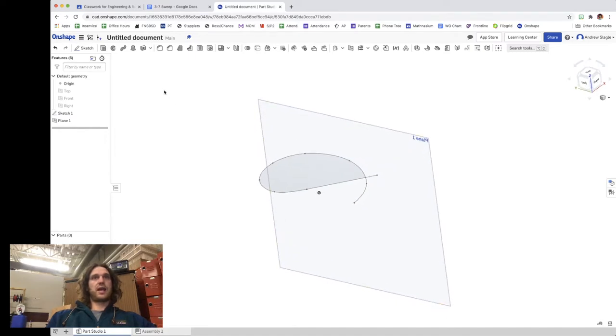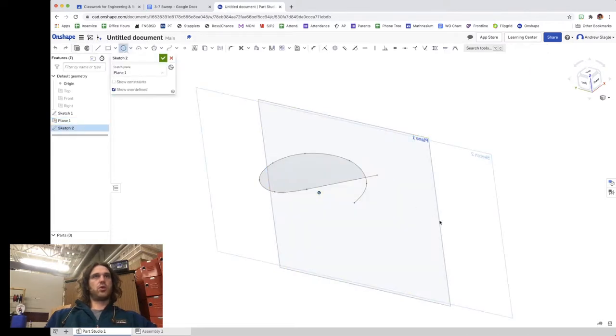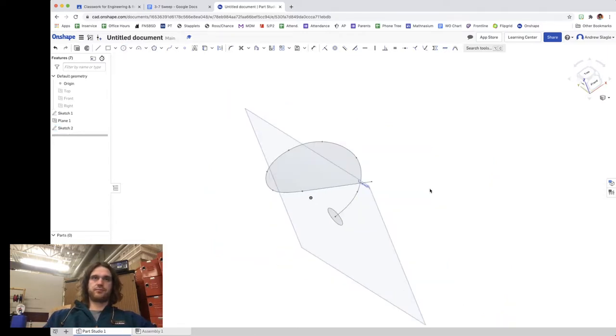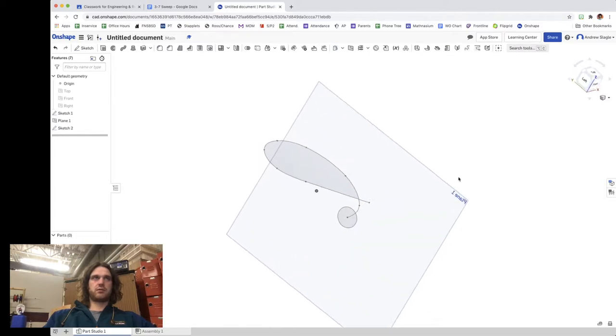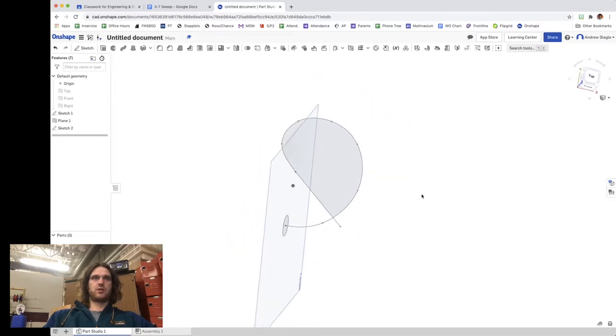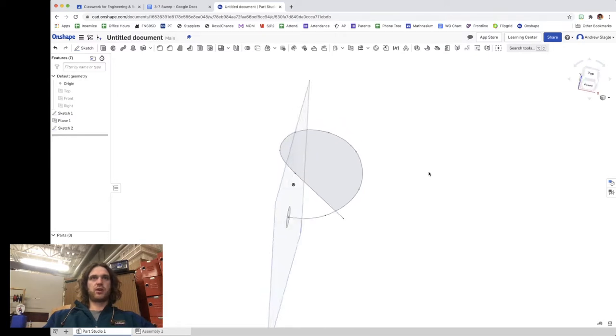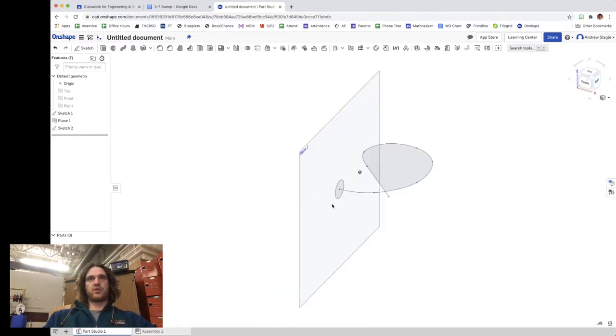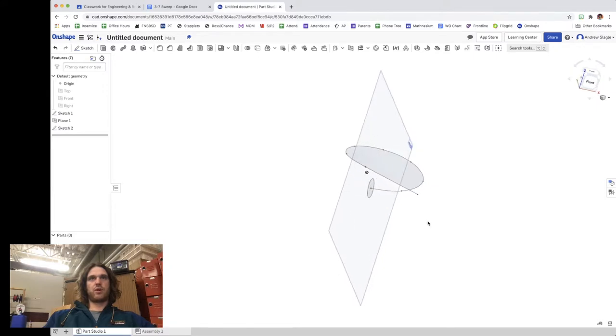And so what we're able to do is sweep a profile. I'm going to be sweeping a circle, so I'm going to create a sketch, grab the old circle tool, and I want to be consistent with what I'm drawing. So I'll make the thickness of my pretzel maybe like 0.65 inches. I think they're usually about an inch. A little thin, that's all right. Dainty pretzel, that's okay. So I got my pretzel here. I'm gonna be sweeping that throughout that shape.